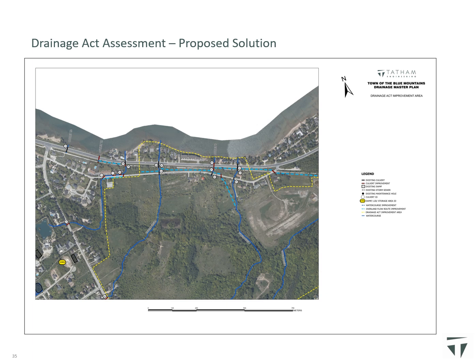An existing spill from watercourse 7 towards watercourse 6 will be eliminated, thereby incrementally improving flooding along watercourse 6, and an overflow channel will be constructed along watercourse 7 and Lakeshore Road to convey flow exceeding the capacity of watercourse 7 from watercourse 7 to outlet 8. The culverts crossing Georgian Trail and Highway 26 along outlet 8 will be improved to convey the additional flow directed to outlet 8 by the proposed overflow channels.